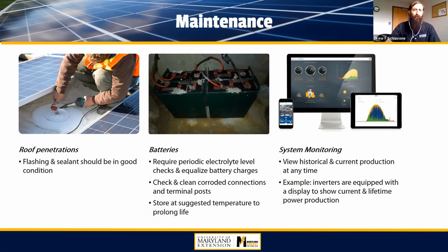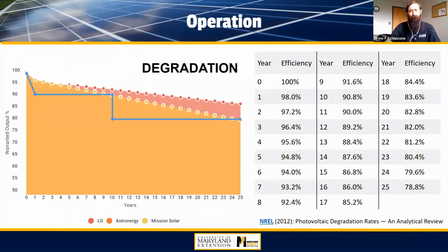Again, a couple other things: batteries, and we'll talk about that another time. Water leakage into your roof, you'd have to reseal that. Not too common, but that's a possibility. Even if you maintain your system really well, you'll still have performance drop over time, maybe 0.5% per year on average, but that's just how it works. And if you drop significantly, you may have the product under warranty, so the module could be replaced. The inverter will also have performance drop. So just look at that over time and see if the efficiency has dropped enough to replace a system.